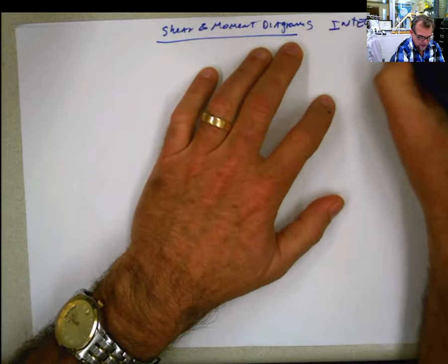That's why it's important that you keep your diagram and you start doing your diagram: plot, calculate, plot, calculate, plot. So the value is 0.75. That means this value is going to be 0.75 kilonewton. Now remember, this span AC goes from 0 to 2. That means that at 0 it is 0.75 kilonewton, and at 2 it is 0.75 kilonewton, because it doesn't depend on x at all.